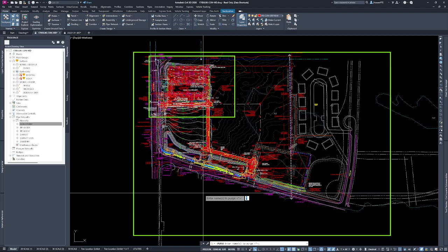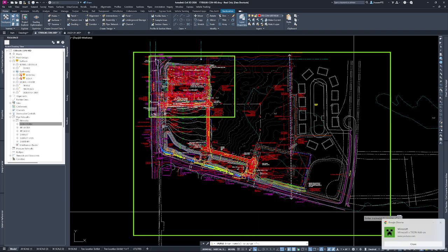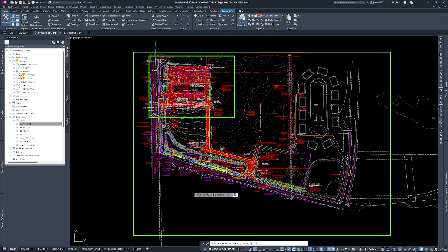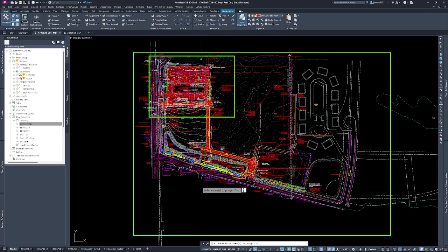From what I can find, Revit is a very big cause of these reg apps. So if you get an architectural plan in, or maybe a Vectorworks software plan in, they may have a translation type thing, and these reg apps get stuck in there, and they just hog up space. You can't use them. We can't see them. There's no other way to get rid of them except for this way.